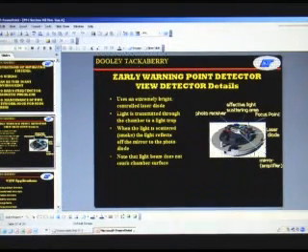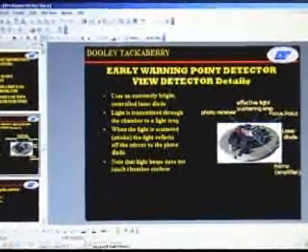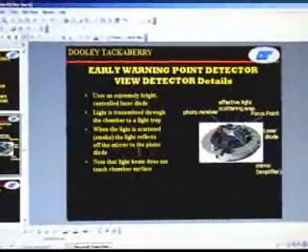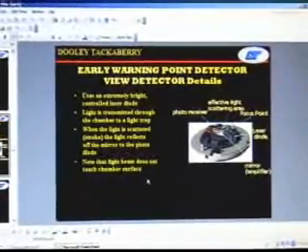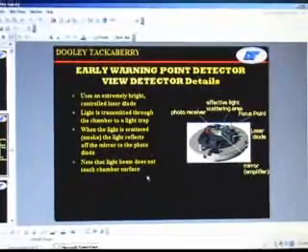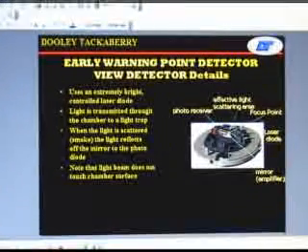And this is the other type of laser detector, they call it point detectors. It uses an extremely bright controlled laser diode. Light is transmitted through the chamber to a light trap. When the light is scattered by smoke, it reflects off the mirror to the photodiode. Note that the light beam does not touch the chamber surface. That's why they call it a point detector.